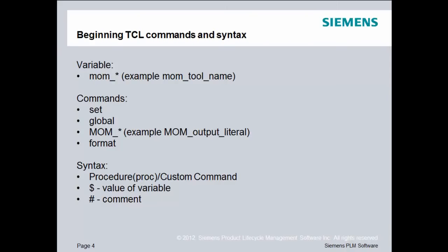Now, what is a variable? Well, a variable is like your phone number on your cell phone. The phone number is not you, but when somebody calls that number, they get to talk to you. A variable holds information. In the case of a phone, a variable allows you to contact the person you want to call. In the case of PostBuilder, a variable allows you to use the information that's stored by that variable.